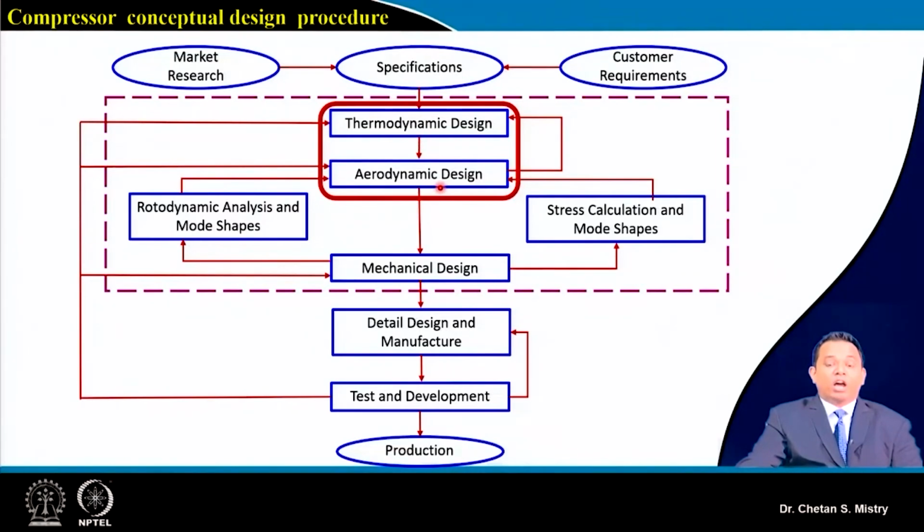Now there is one more aspect, which is called mechanical design. We are not covering that in this course, because this course is dedicated to aerodynamic design only. But when we talk about making the rotor and stator, mechanical design is equally important. Suppose we consider a rotor: it is fixed at the hub and the other end is free, so it acts like a cantilever beam.